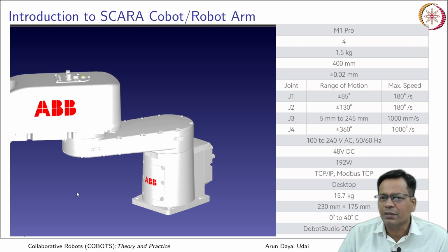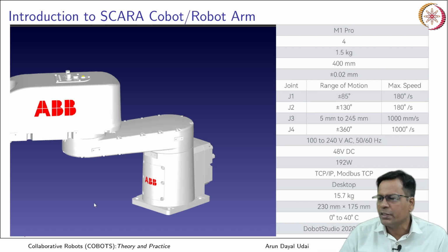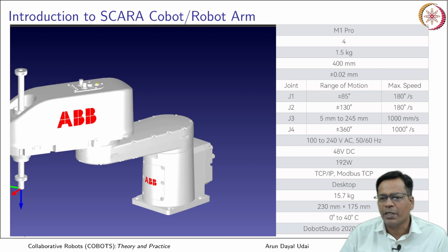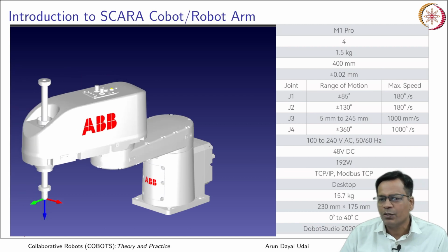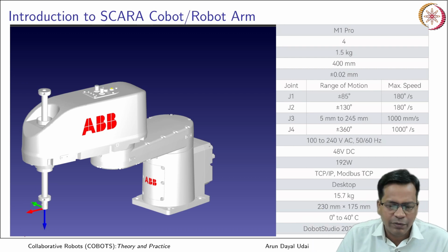So that is the reason it is very popular in the industry for pick and place, vertical pick and place operation in the industry, like, okay, PCB assembly. So you can pick up a chip, you place it on the board, you just need some motion like yaw motion, okay. You don't need many other motion. So this is the yaw motion to orient your chip. It can pick from a place and it can put it anywhere, okay. So you pick it, you place it, pick it, place it, so that way it is very, very fast.